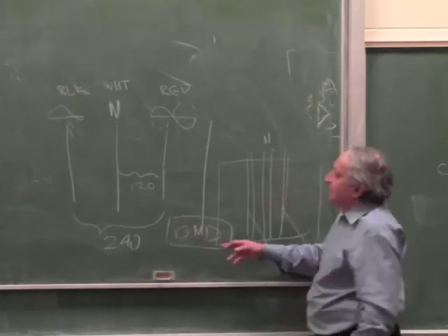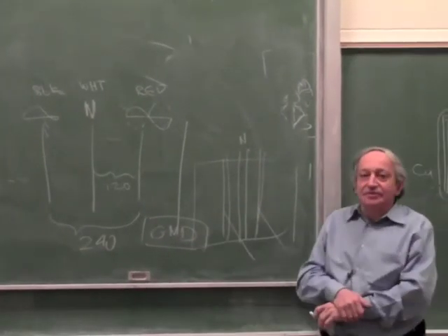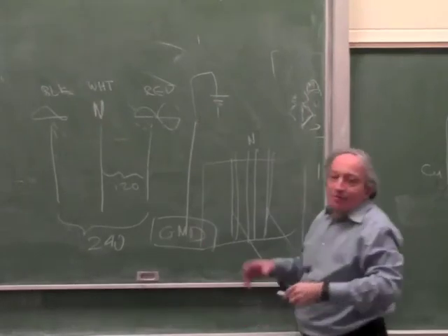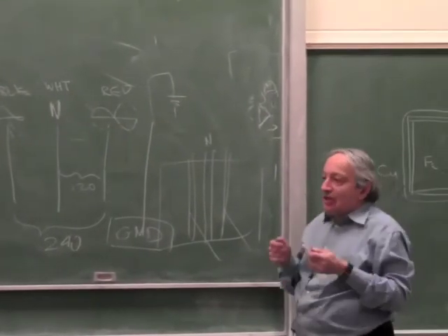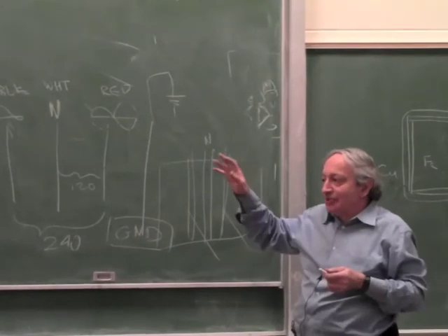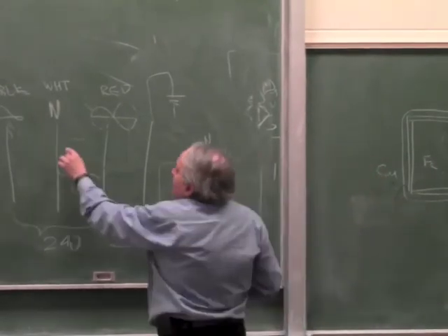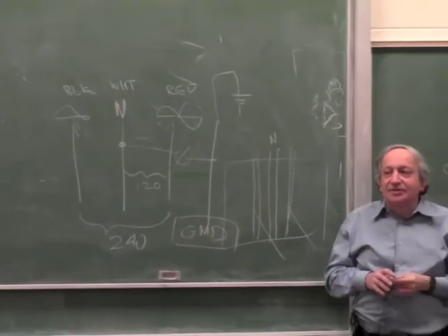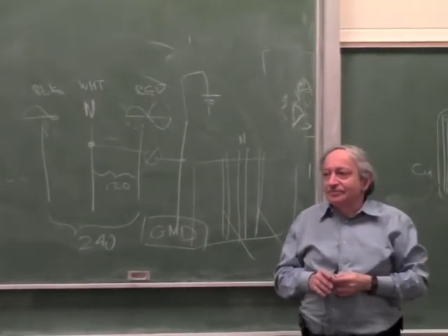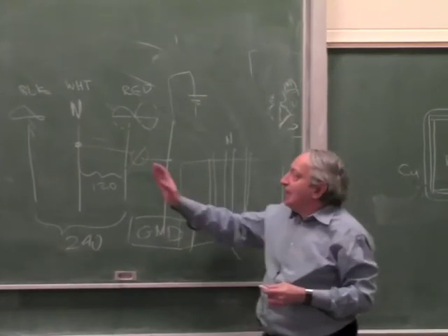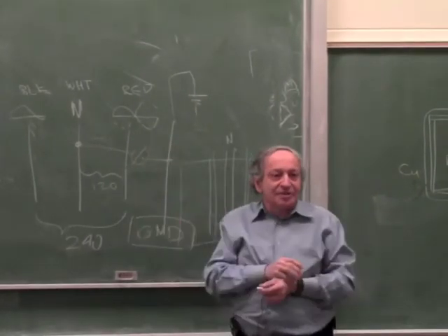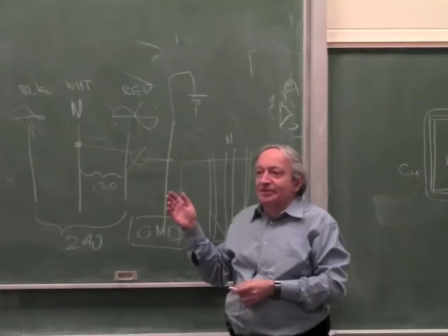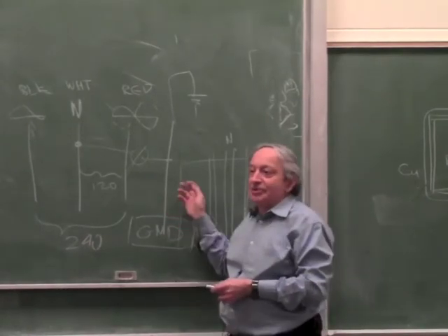What is this ground wire connected to? To ground, basically, somewhere to a pole, to a pipe, into the ground. Now, when you shut down the power to your house, let's say the house is not powered, and you take an ohm meter and measure between the neutral and the ground, what resistance will you get? Is the neutral isolated from the ground or not in a house? Open circuit. How many people say open circuit? And how many people say short between the neutral and ground?